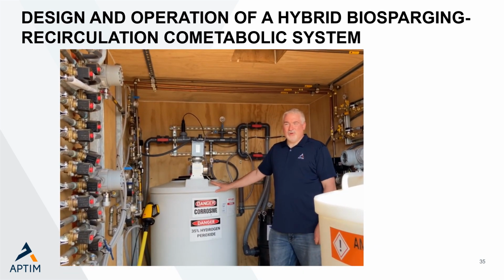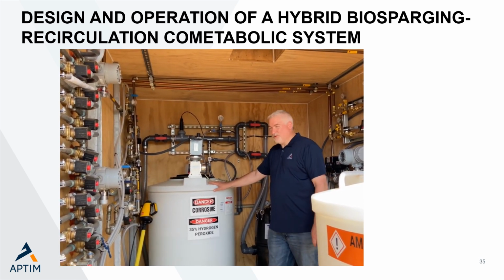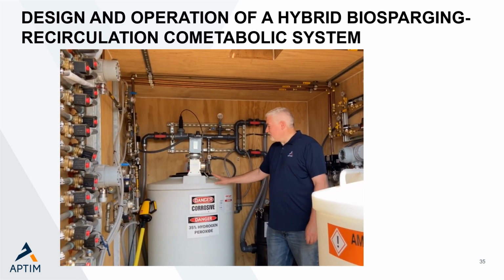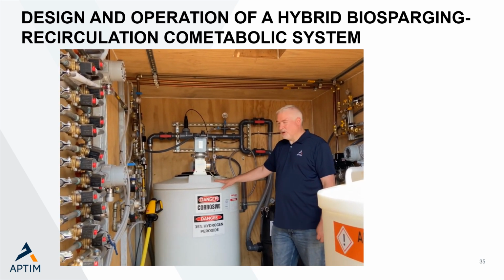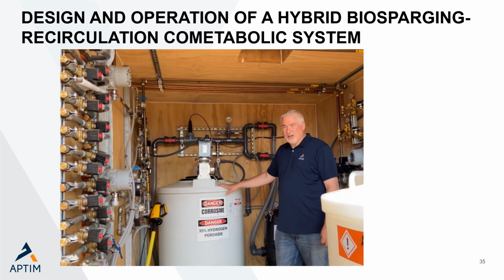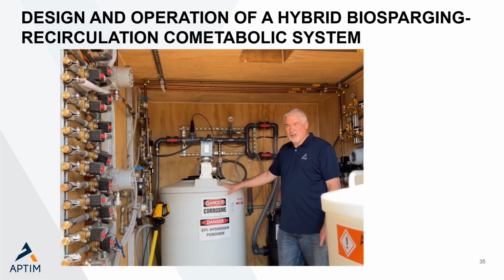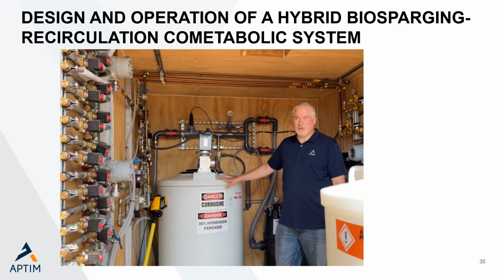Biofouling control is important in any of these systems, and the way we do that is through the addition of hydrogen peroxide. This system operates approximately 12 to 13 hours a day. Because it's run off of solar, we don't run it all night long. So at the end of each cycle, we add 600 ppm of hydrogen peroxide to the system for approximately 20 minutes.